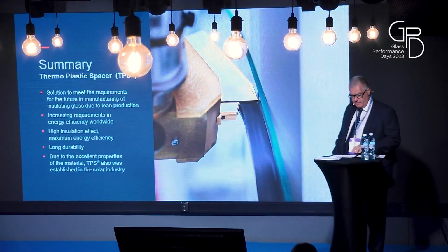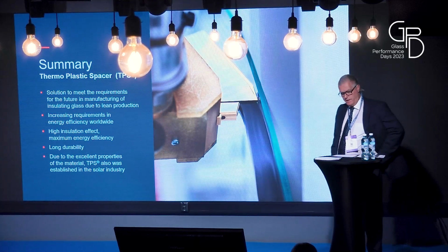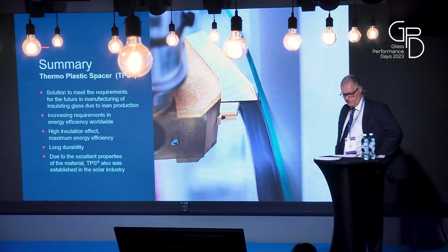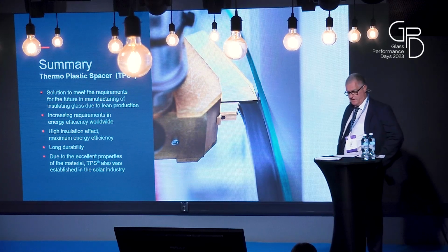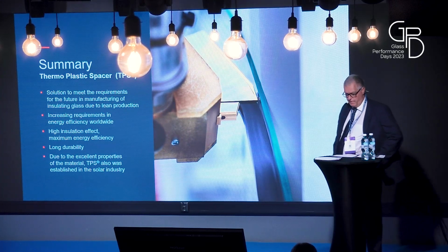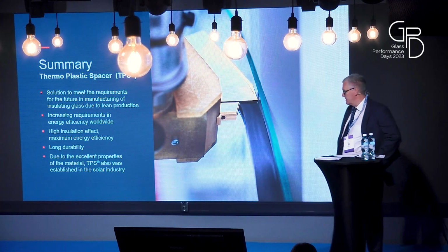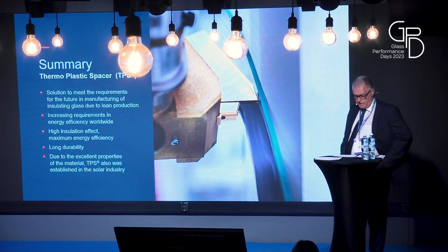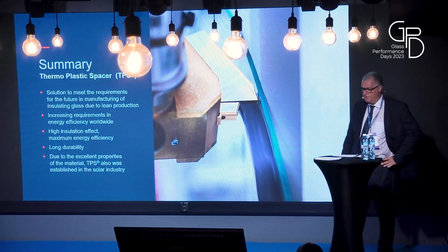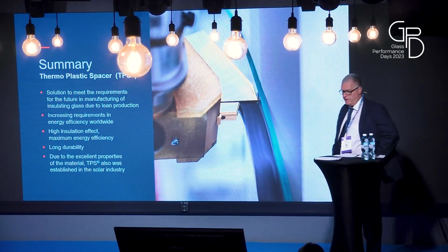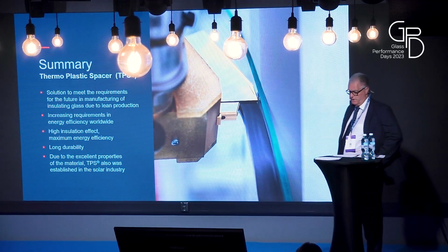We have seen what kind of advantages and benefits there are with TPS technology. Not only the process, also the final product: gas tightness, warm edge spacer, flexible for heat-cold changes. In our perspective, with these presented properties, it is definitely the best solution to meet the requirements for the future for the manufacturing of insulating glass production process.